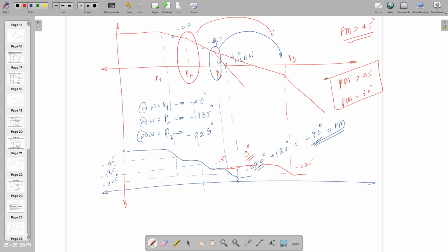However, sometimes it depends, because taking all these things outside in the frequency domain is actually costing in terms of current. So we'll see in later stages how to take these poles outside UGBW, because it's costing current or it's costing area. So it's not a wise decision sometimes to take the pole much higher than UGBW to achieve a phase margin of 90 degrees. If you are happy with 60 degrees, that is also good enough, because that is going to reduce some power, right?